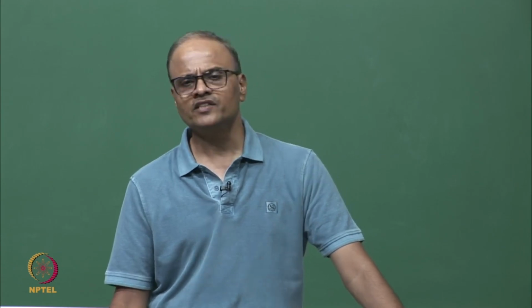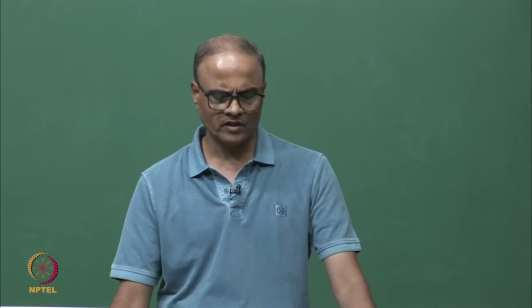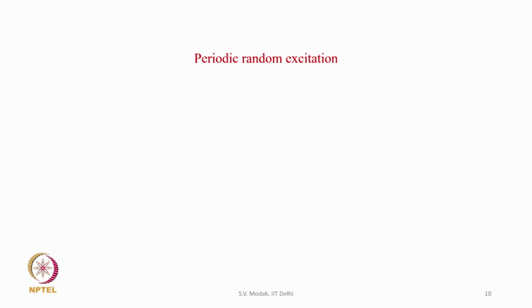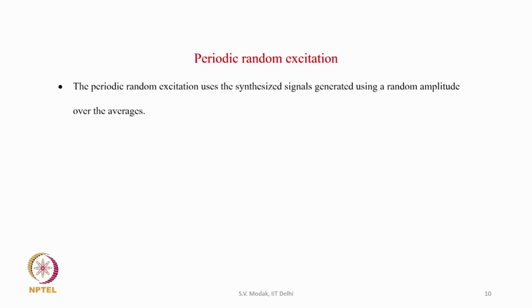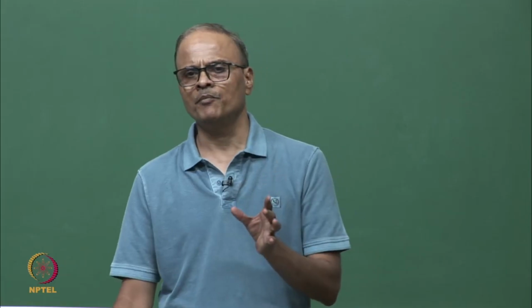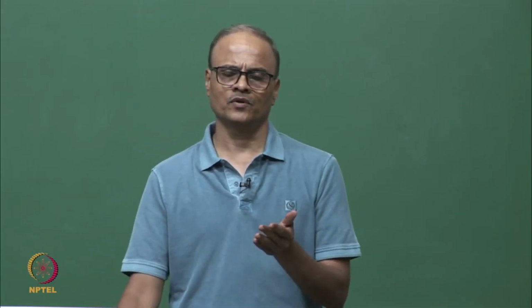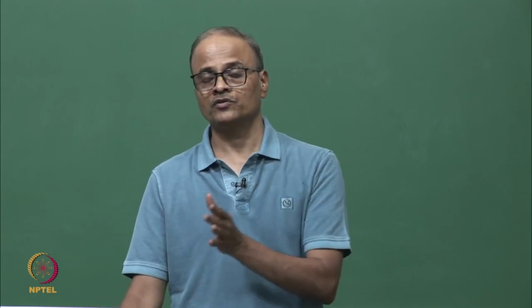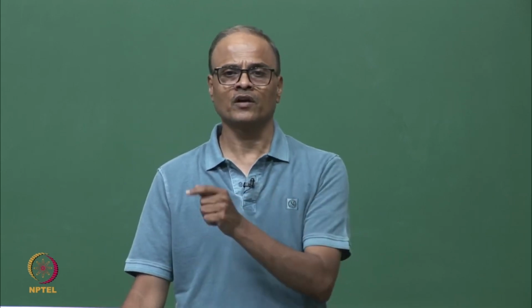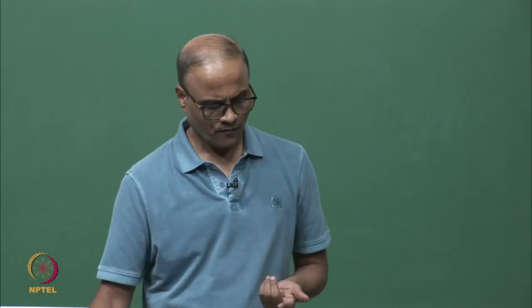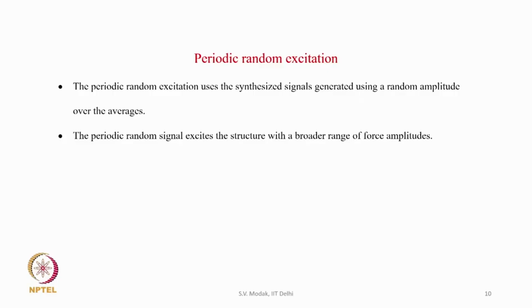In order to address this shortcoming of the pseudo random excitation signal, periodic random excitation has been developed. So, what is periodic random excitation? The periodic random excitation uses synthesized signals which are generated using a random amplitude over the averages. What we do is change the amplitude of the force while generating the excitation signal from average to average. Therefore, a different force amplitude is used for every average.